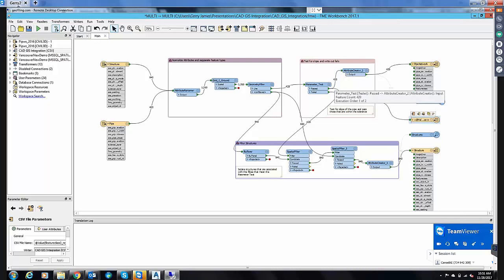So these kinds of things are important when you're trying to move data between that Civil 3D environment, where you have a standardized drawing environment, and you can move all that information across. You can push that into the SQL Server database, and you can actually do quality control checks, automate those quality control checks, which will lead into other types of conversations, like we've talked with a lot of our clients about, digital submission frameworks. It also saves a lot of time.